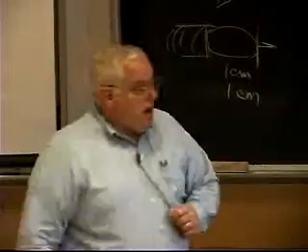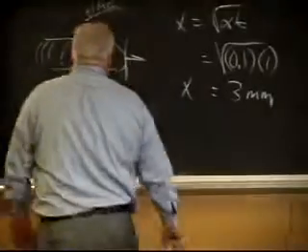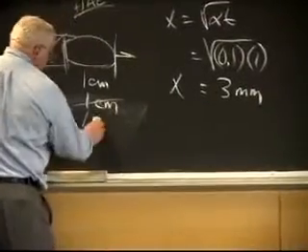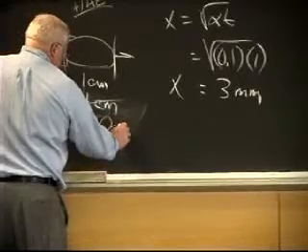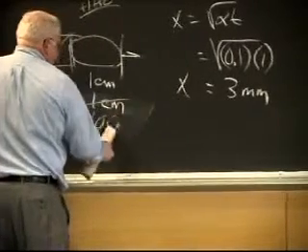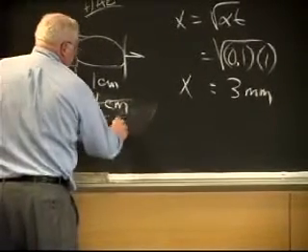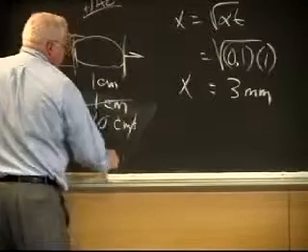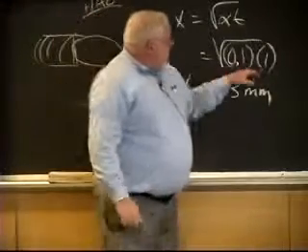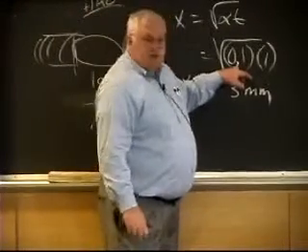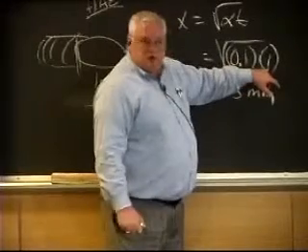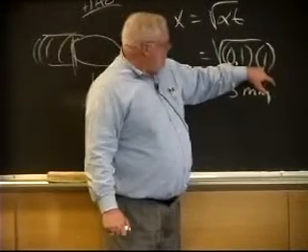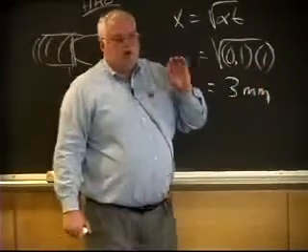Okay. Now let's change this problem and say that I am going with an electron beam weld at, well, let's just do 10 centimeters per second. That means this is now, this is still a tenth for steel. This is now a tenth of a second. And so this becomes 1 millimeter.